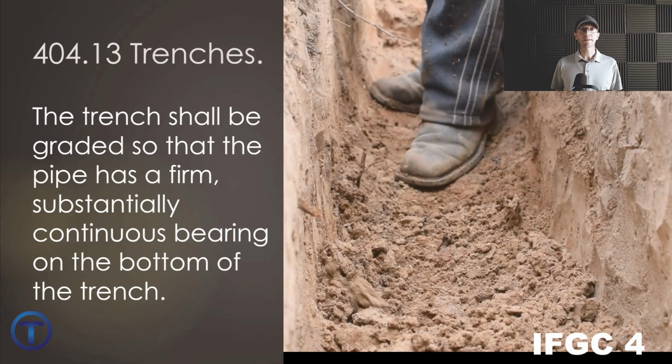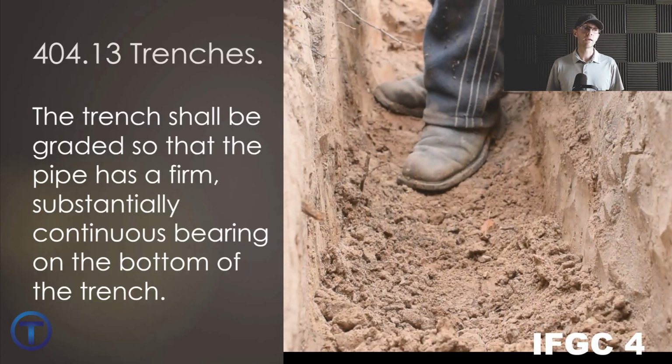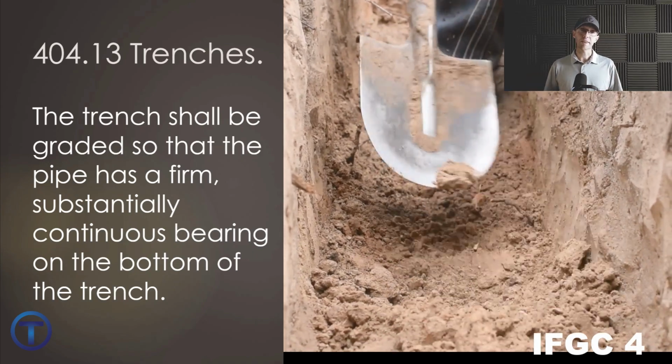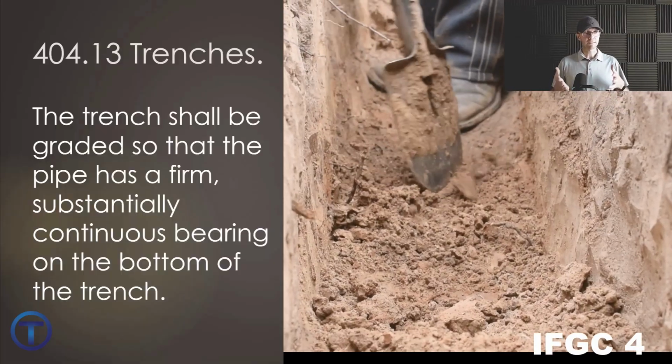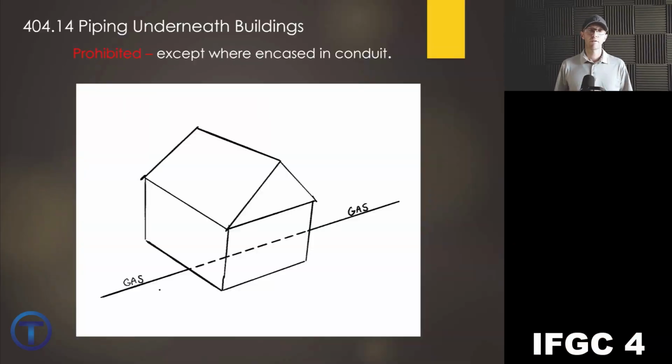As with any piping that is installed below ground, when we have that trench open and we lay the pipe in it, we have to make sure that it's properly supported. So this 404.13 states that the trench shall be graded so that the pipe is firm and substantially and continuously bearing on the bottom of the trench. 404.14 talks about piping underneath buildings. We talk about running pipe below ground, but can you run a gas line right under a building? The answer is no. Running a pipe below a building is prohibited other than the exceptions we've talked about earlier where it's encased in a conduit.